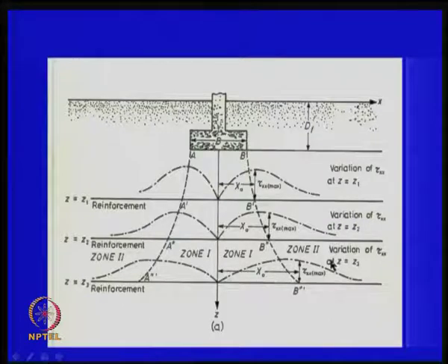Okay. What it means is that you have a foundation system here, and then you have reinforcements like this. That is what we are trying to imagine, that you are placing some reinforcements at some depth. You take the center line of the footing, and based on the elastic stress distribution, as I said, reinforcement causes shear, and shear is important in reinforced soil, right.